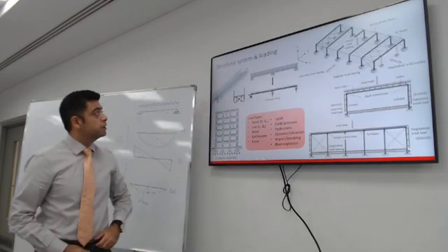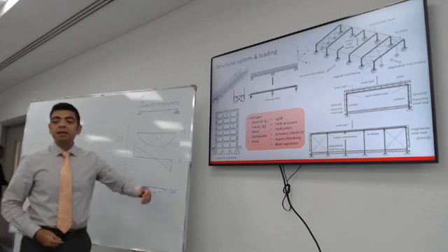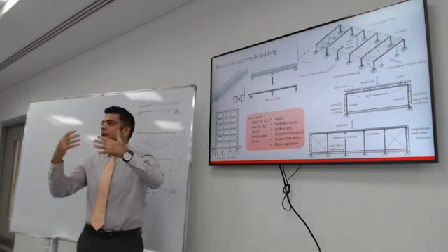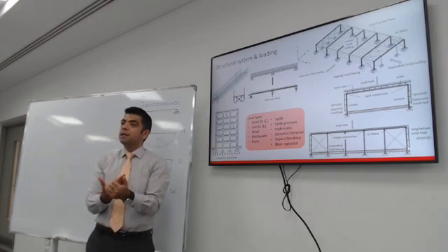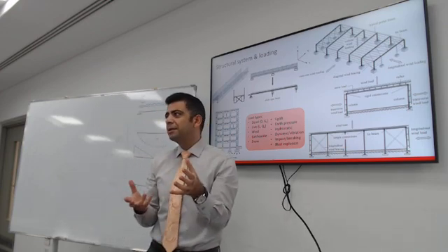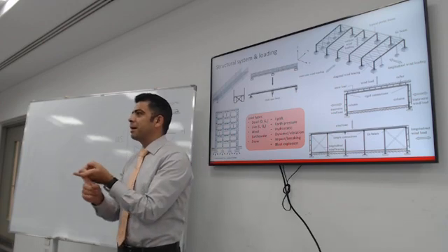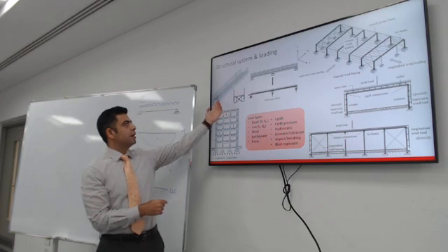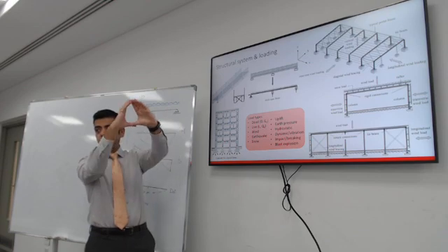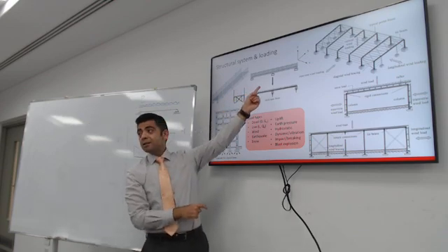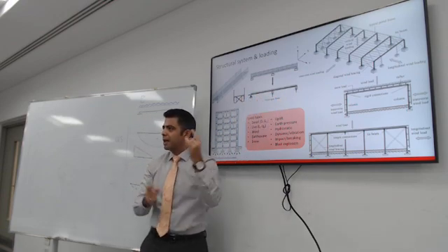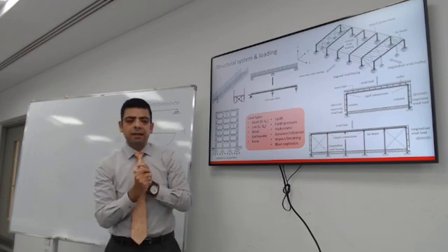So very quickly, let's talk about structural systems. Let's say you're trying to build a bridge. This is the finished product. So how do you break it down into a structural system? A structural system means where are the structural elements? Do you know what the structural elements are? Yes. What are they? Columns and beams. Columns, beams, slabs. Thank you. So where are the beams for this bridge? It's these two tubes. Can you see these rectangular tubes? Yeah. That would be the beam. So your structure analysis would look something like this, a beam on supports. And we know pretty much how to get that. Reactions, distributed load, things like that.